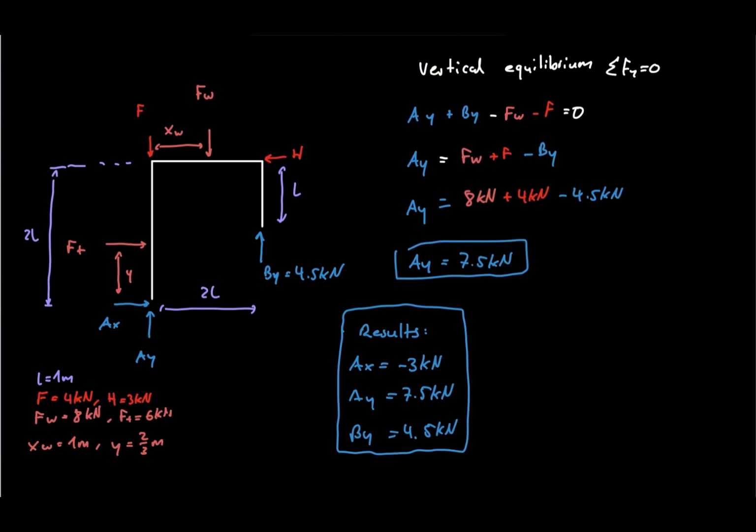The key lesson is that the problem looked difficult because many things happened at once. But nothing new actually happened. Replace the distributed loads, draw a clean free body diagram, apply equilibrium, and check the result. That is the same workflow again,